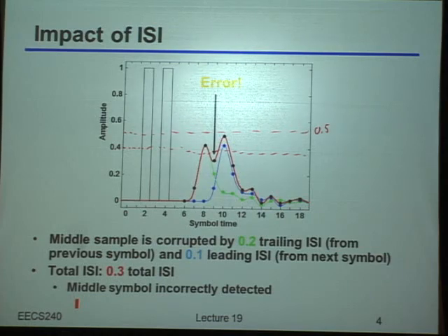Okay, so again, the take-home message here is really that this intersymbol interference can very easily cause you to get bit errors. In other words, simply because of the fact that information from either previous or even quote-unquote future bits is basically messing up the analog waveform that you receive, you no longer can just rely on saying, well, the thing was either above a threshold or below, because as you can see, there's no real unique good answer. Right? Depending upon what exactly I sent, that would actually change which threshold, ideally speaking, I would want to use to get the data stream back. Okay?